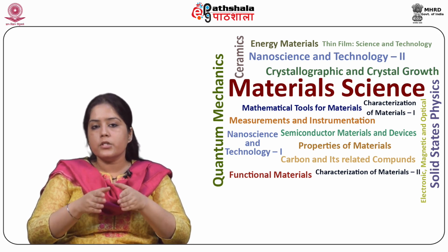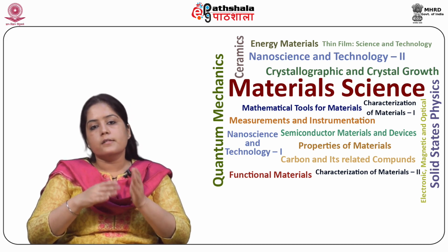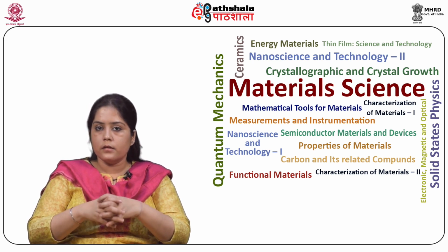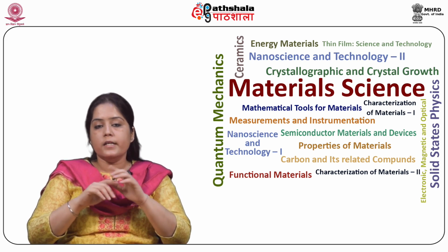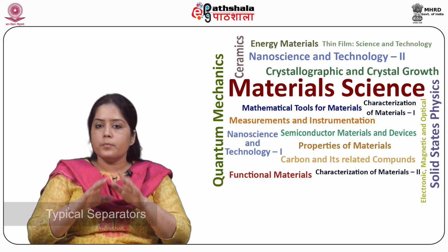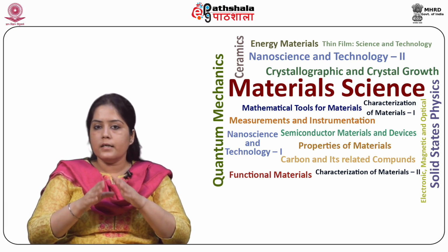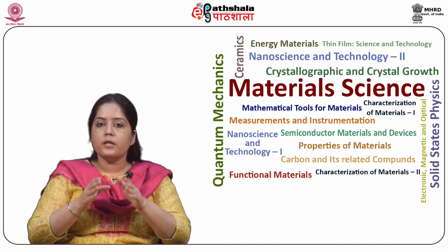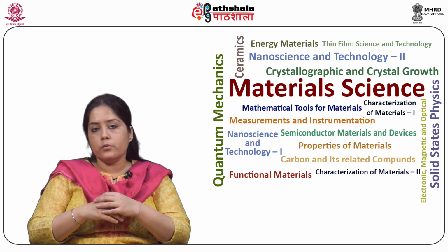Now, the permeation of the active species and the selectivity of the charge carrying ions throughout the separator is highly important. Typical separators for RFB are IEM, which are fabricated from polymeric materials with a pore diameter of about 20 angstrom.